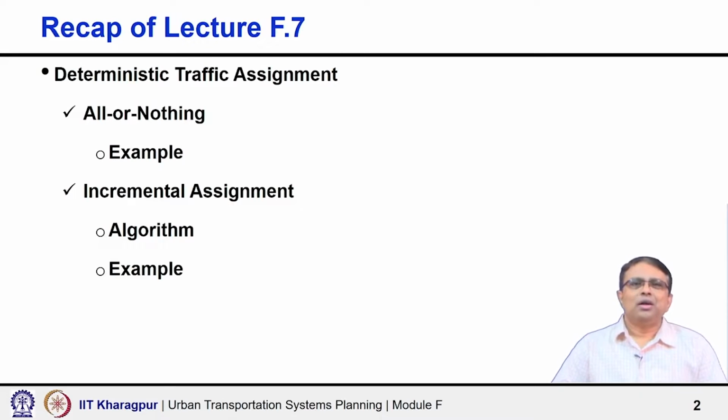So, like this, we can improve the solution to a great extent, but still the true user optimal equilibrium we are unlikely to get, because even the last increment may distort the whole thing very drastically, depending on at which point the road is operating. Even a small increment may have a bigger impact if the loading is at or near the capacity.